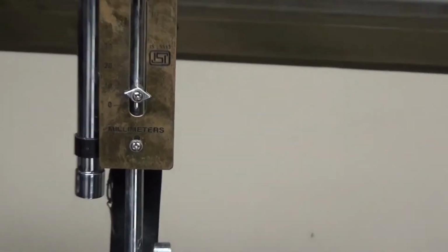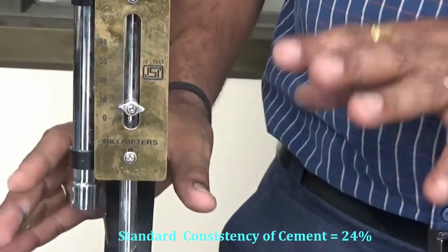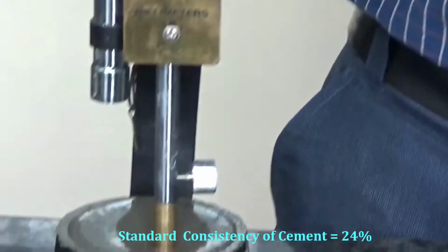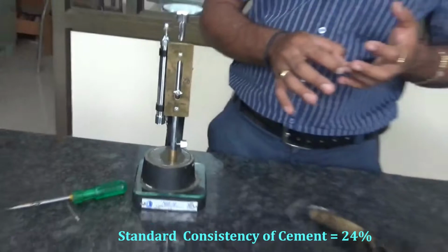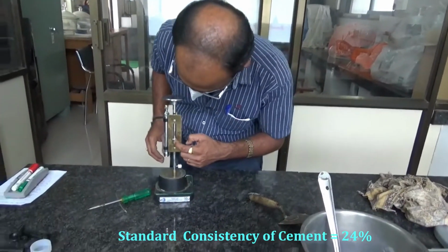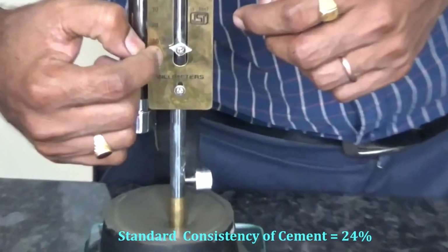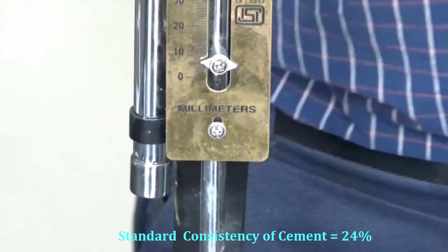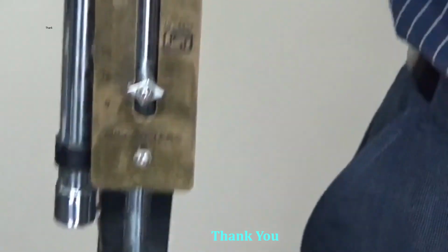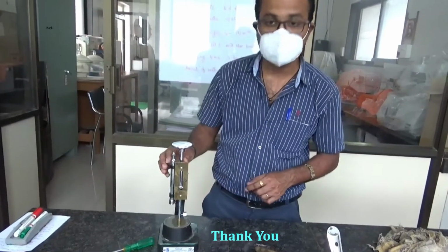So the standard consistency of this cement paste is 24%. We have done a trial with 27%, then 25%, and the third trial was 24%. For 24% we got the reading as 6 from the bottom. So this experiment is over. In the next practical session we will see how to determine the initial setting time and the final setting time. Thank you students.